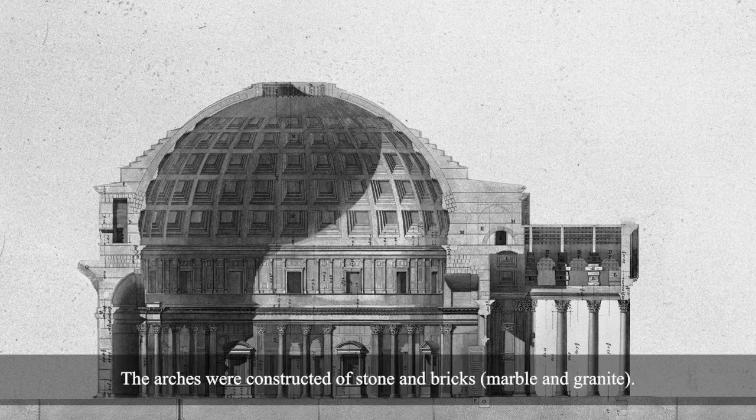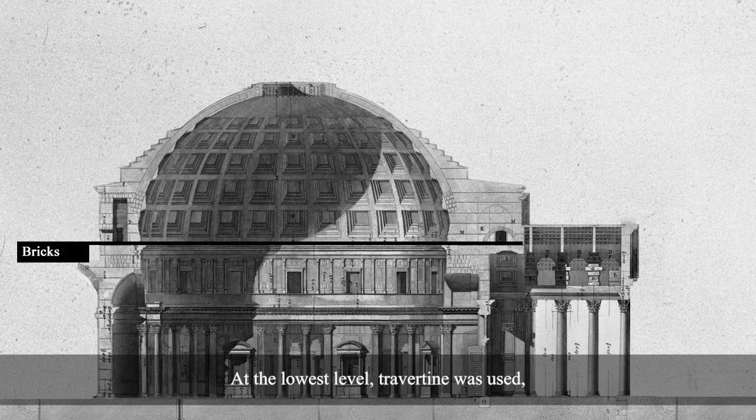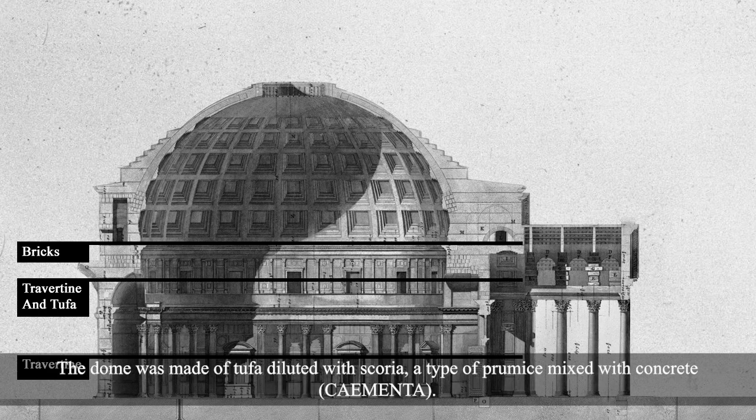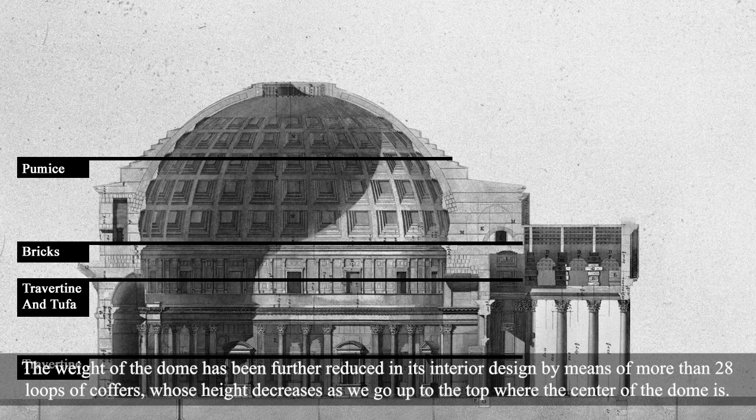The arches were constructed of stone and bricks, marble and granite. At the lowest level, travertine was used. Then, a mixture of it was used with tufa. Then, tufa with bricks. Then only bricks were used in the construction of the drum section of the dome. The dome was made of tufa diluted with scoria, a type of pumice, mixed with concrete. The weight of the dome has been further reduced in its interior design by means of more than 28 loops of coffers, whose height decreases as we go up to the top, where the center of the dome is.